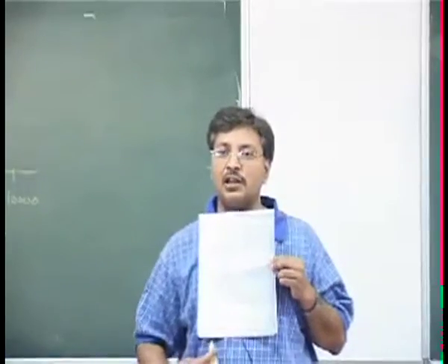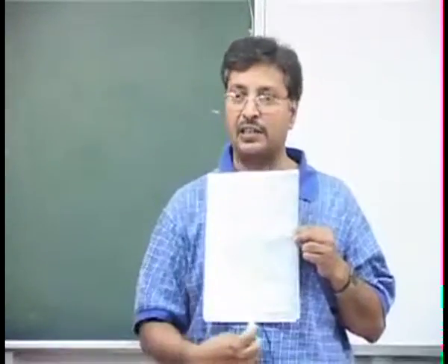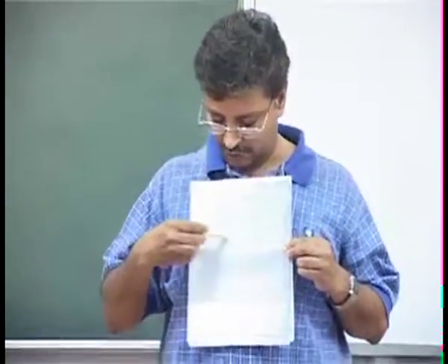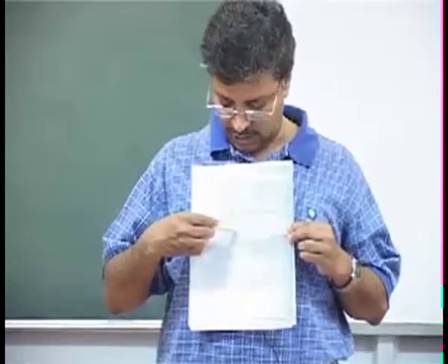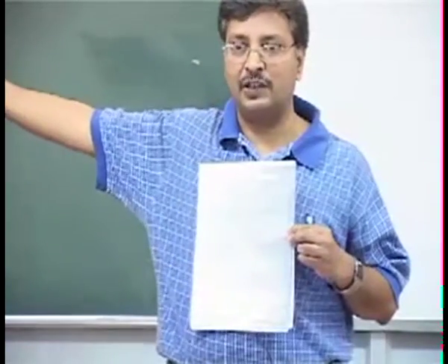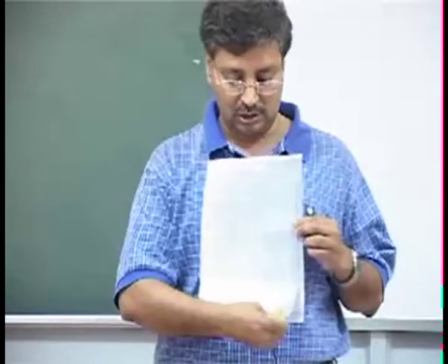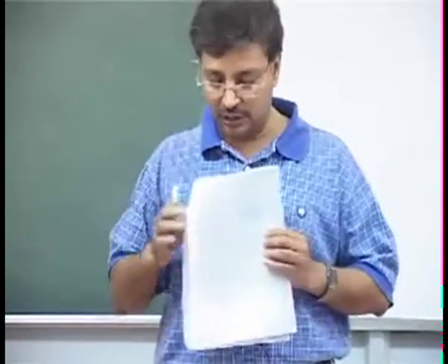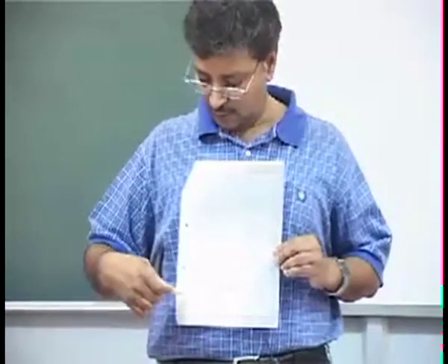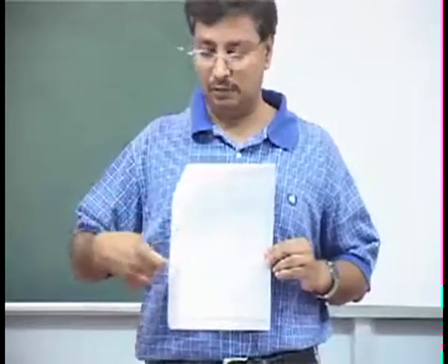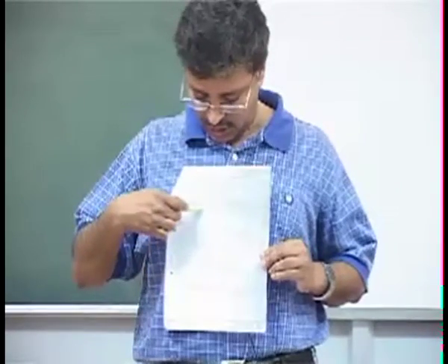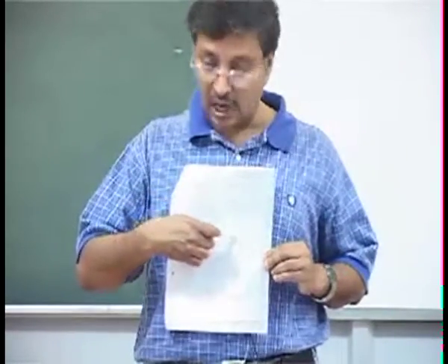This axis is the downwind distance x, and this side is sigma y, and these are the values of sigma y for stability A, B, C, D, E and F. And then the same thing for sigma z, where you see more curved graphs, with the same downwind distance on the log scale and the value of sigma z on the y axis, again on a log scale, for A, B, C, D, E and F.